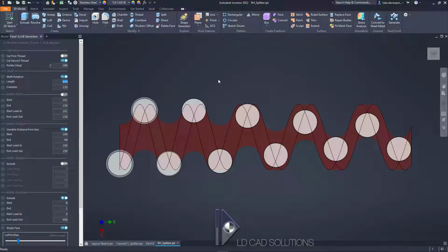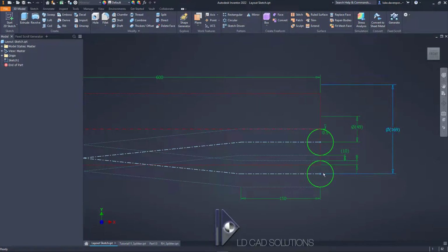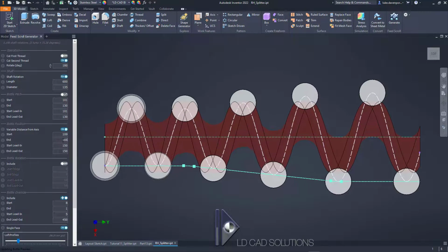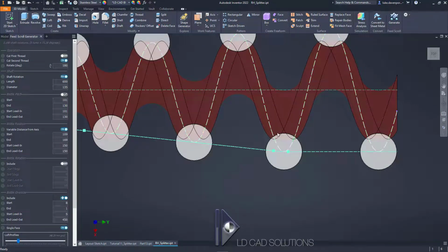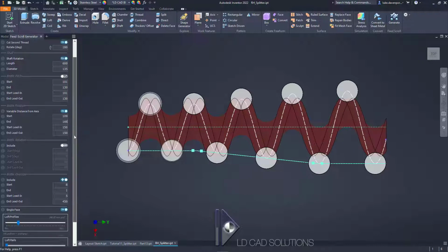So let's head back to our layout sketch. We've cut the inner root, we're now cutting the outer root, which has a position of the bottles of 169 millimeters on the diameter for the center of the bottle there. So let's head back here, and we want to specify that here. That is, instead of 49 millimeters, 169. Hit enter. Okay, and we can see that we do have some shaft contact with the bottles here, so that it will be pushing the bottles out towards the outer path here, and we're pretty much ready to hit generate and create this second root here.